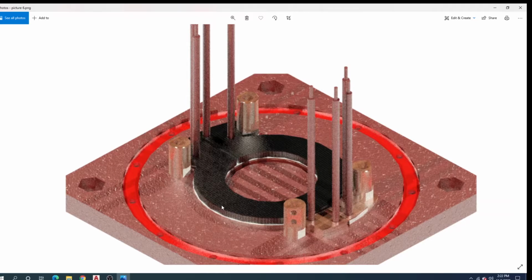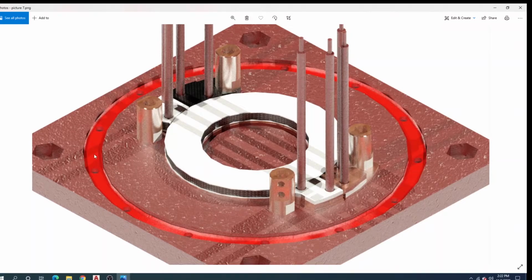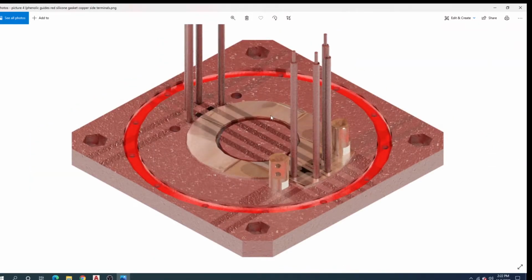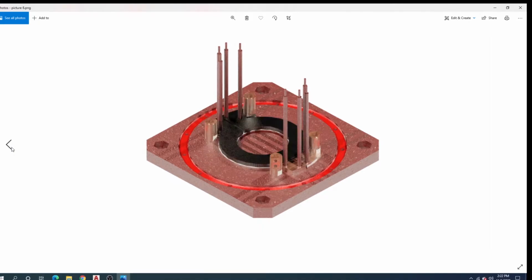These are 1/4 inch thick, whereas the copper layers are 1/16 of an inch thick. And the reason for that is because iron has a higher resistivity than copper. So basically electricity encounters more resistance as it flows through iron relative to that of copper.